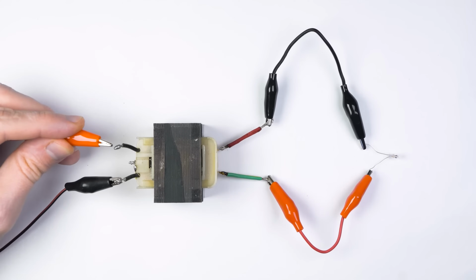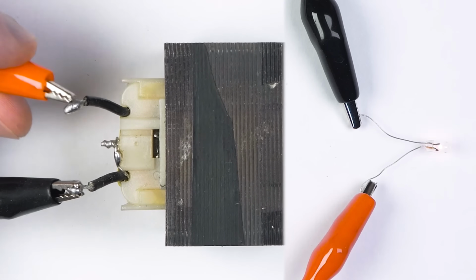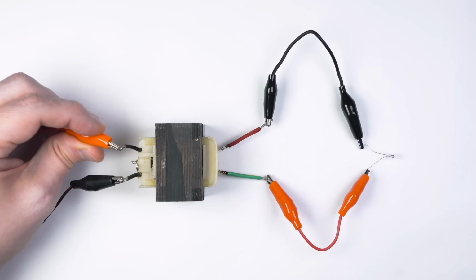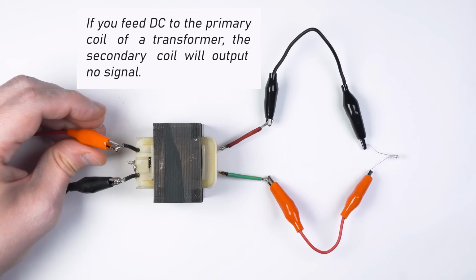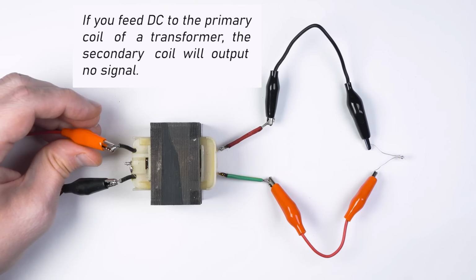A transformer can only operate on alternating current. If you connect a light bulb to the secondary coil and a battery to the primary coil, the bulb will only flash once, but will not glow constantly. This is because transformers only transfer energy while the magnetic field inside the magnetic circuit is being changed, and the direct current cannot provide such change.